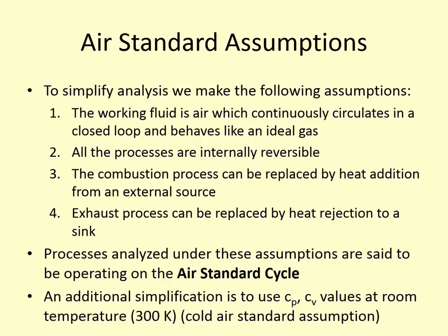So the air standard assumptions are fourfold. The first, the working fluid is air, which continuously circulates in a closed loop and behaves like an ideal gas. So in reality, with a real engine, we're intaking air, mixing it with fuel, combusting it, and then exhausting fuel gases. And it's not a closed cycle, it's an open cycle where we have fresh air coming in and exhaust gases going out. Well, for the idealized cycle, we're saying, let's just imagine that the air that comes in is the same air that just left, because we're not worried about how much fuel to air ratio there is or what's in the exhaust gases. We're just calling it all air. So we're just going to assume that it's the same air.